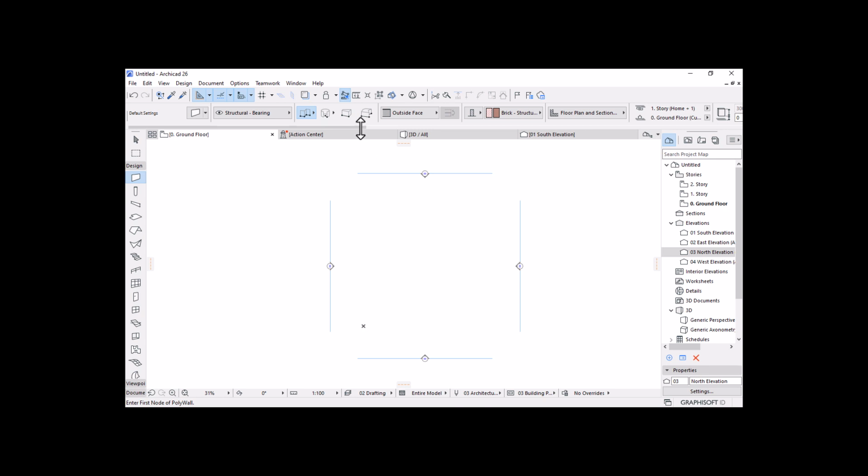We have different types of placement geometry methods in ArchiCAD. If you click on this arrow here, it will show you different types of geometries under drawing a single wall. The first one is point by point: you specify 2 points to click and place just a straight wall. Then we have this one where you can use multiple points to create multiple walls, and this rectangle box to create a box or a slanted box, which is the last one. So I'm going to activate multiple walls at the same time, because that's what we want to achieve. Once you are done here, it's time to start placing this wall.